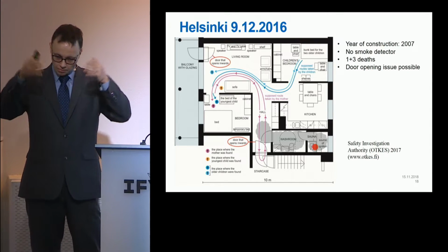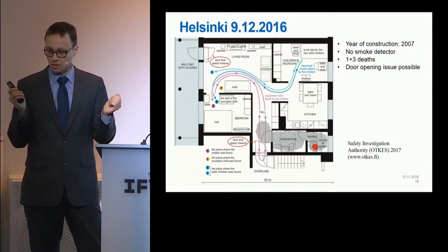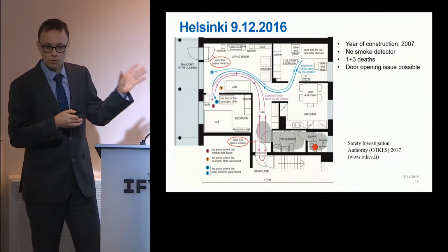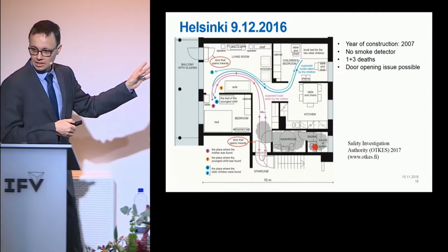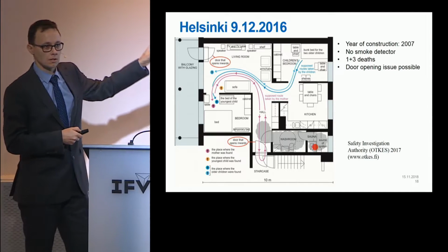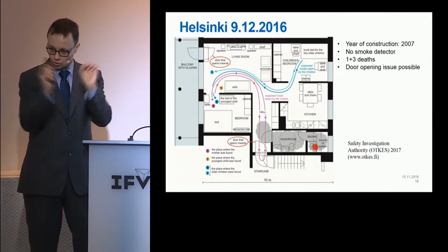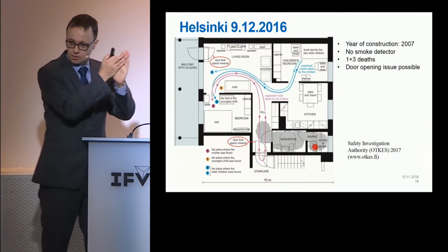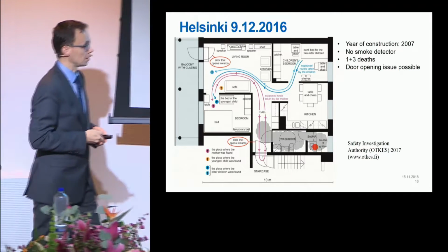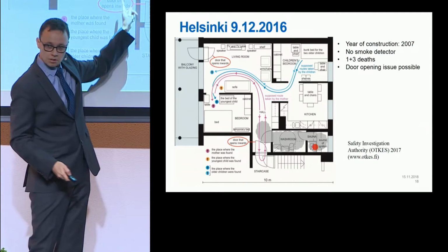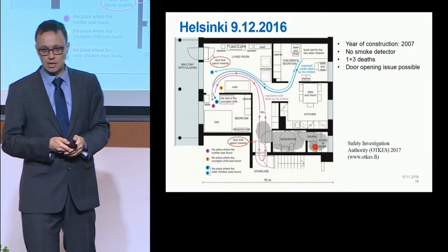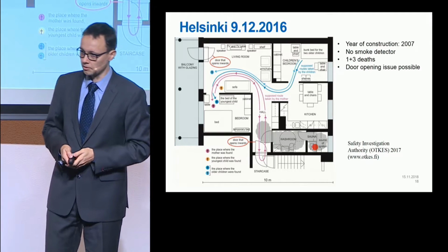Also, the soot flow patterns outside the door are exactly like what we saw in our experiments, indicating that the overpressure was of the same range. There was the same kind of flow of sooty gas from the gaps of the door. As a consequence, inwards opening doors in the apartments of Finnish buildings have been abandoned in the building code from the beginning of this year.